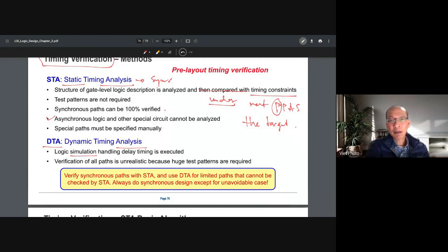And nowadays we are not only checking the timing, but the power too. So there's STA, they call that static timing analysis, right? But the tools also include PrimeTime, and you have PTPX, like PrimeTime Power, which measures the power too. And those are tools from Synopsys. So STA is a static timing analysis. It's the static one, so it doesn't use simulation, so it will be faster.